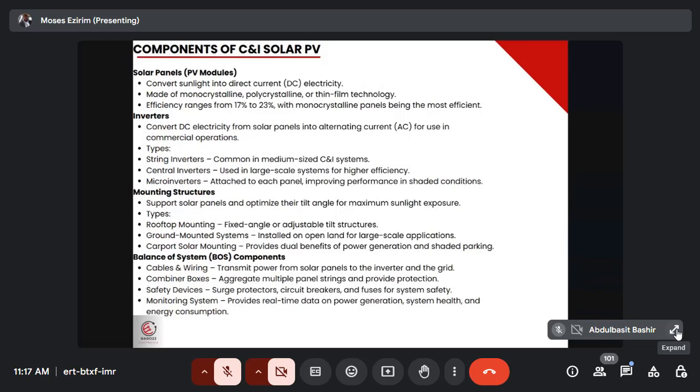Let me use, for example, your breaker. Instead of you to use 16 amps breaker, you are using 5 amps breaker because you feel everybody's just using breaker, no need for me to size it. I've visited a particular installation and I'm seeing the 5 amps breaker. Okay, let me use 5 amp breaker. What will happen? That breaker will heat up because of the current that is passing through it. The breaker might not even heat up. What will happen? It will trip.